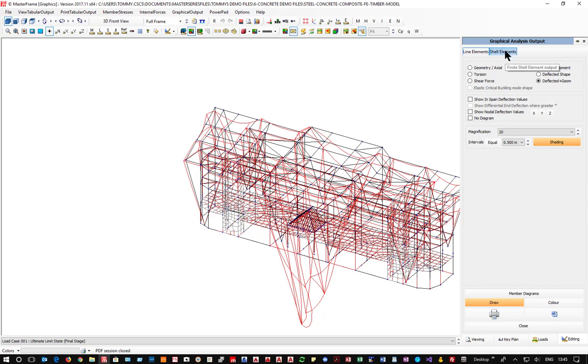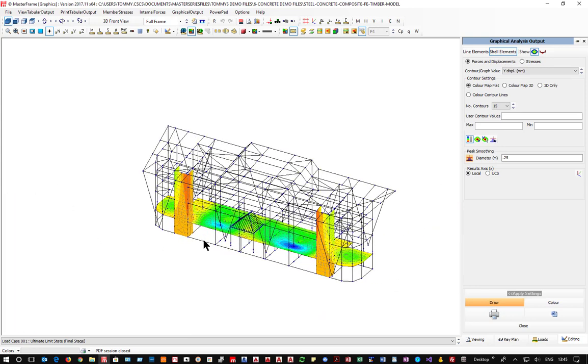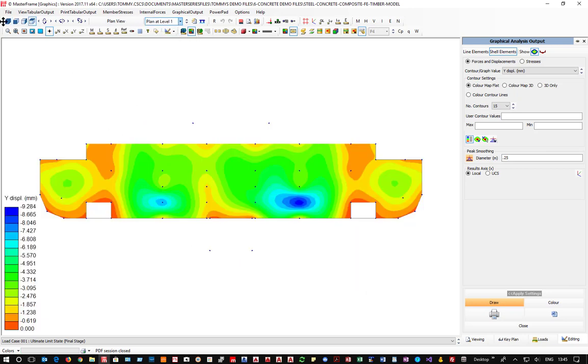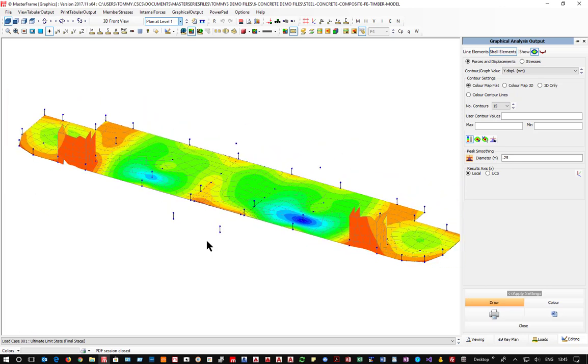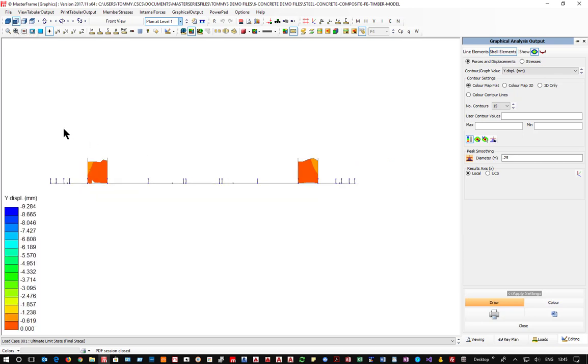So now I'm going to go to shell elements, and here we see immediately some nice pretty diagrams. Now I'm going to initially forget about the 2 columns and just come straight to level 1. So there we go, there is our little FE surface, and now it's taking those upper and lower, and I'm just going to refine that view very gently and just do that.